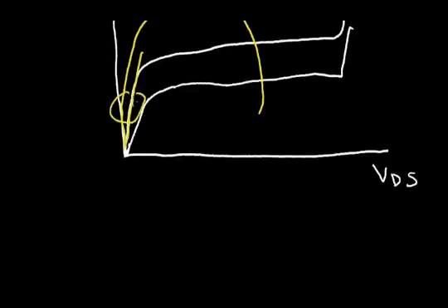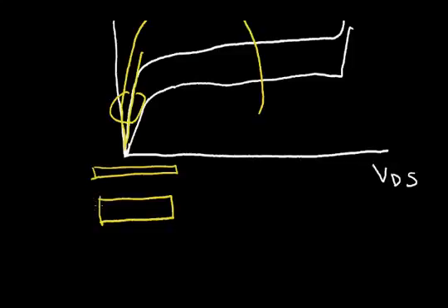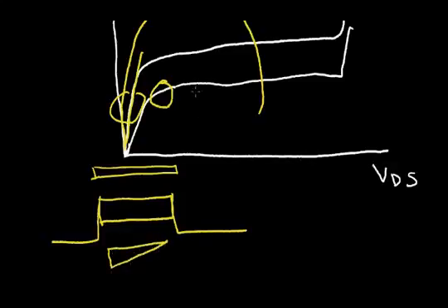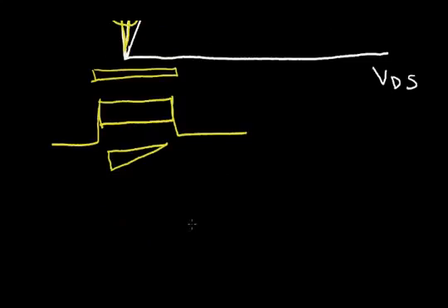And in this part of the curve, you can think of the channel as just being a bar of silicon, where the gate electrode is up here and the source and the drain regions are here. So now in this part of the curve, the channel is more like this. It gets pinched off. And over here, the channel is deep over here and will even pinch off sooner.